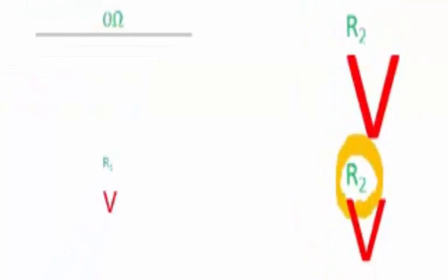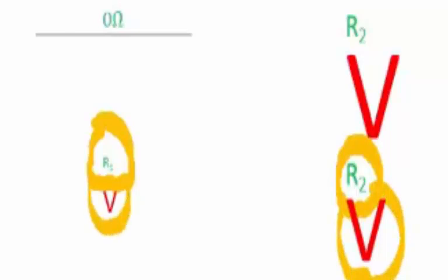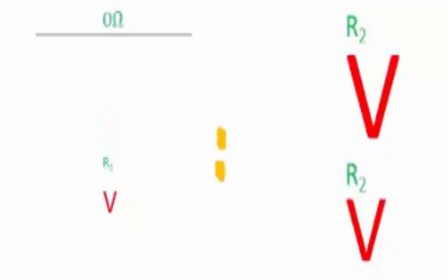If resistor 2 has a greater resistance relative to resistor 1, resistor 2 is greedier in comparison to resistor 1, so it will take more of the voltage than resistor 1 takes. Put another way, the ratio between resistor 1 and resistor 2 lies more heavily on the side of resistor 2, so it will take a greater proportion of the supplied voltage.